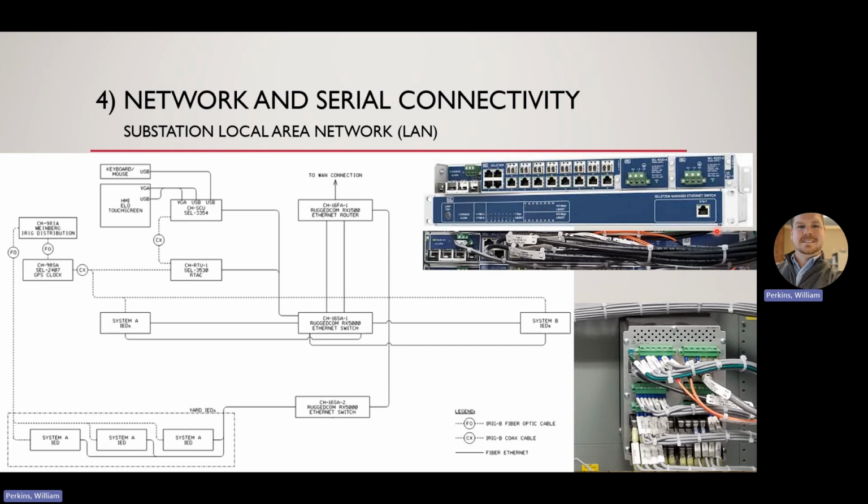Or in other instances, there is a local area network, which is comprised of either a single switch or multiple switches, which IEDs utilize their network ports to talk back to the switch, in which the switch is then connected to the RTU. So within the local area network, the IEDs also have the ability to communicate to all the other devices that are on the network.